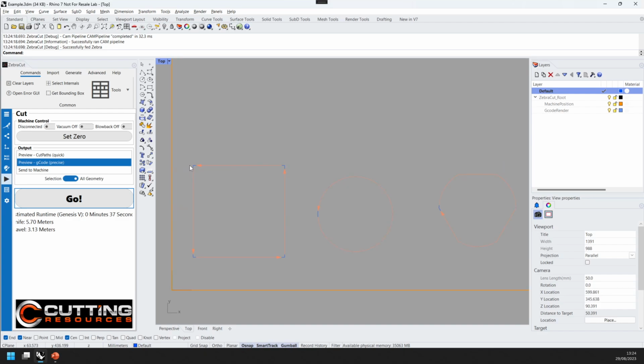You'll see what's happened is for every side of this square we've reduced the start and end of the line by 10 millimeters, and so we don't actually cut right up to the corners. However, because the blade will inherently overcut, we will automatically get corners which join. And that will avoid us cutting outside of the square, for example. The same on our circle.